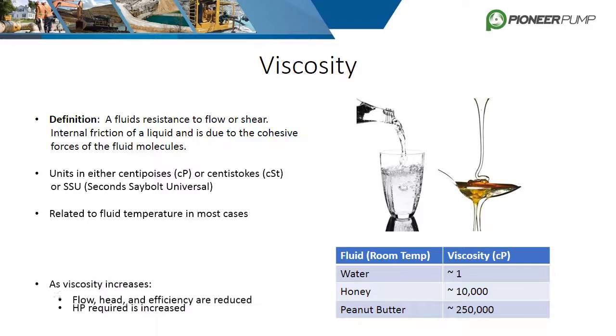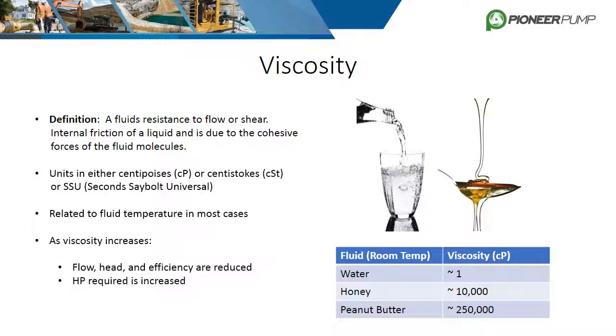it flows easier. Due to the fluid having more internal friction, the fluid will resist movement, causing flow, head, and efficiency to decrease, and horsepower required to increase.